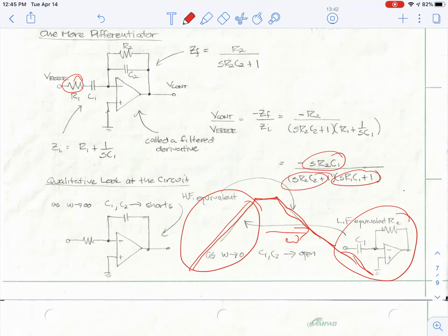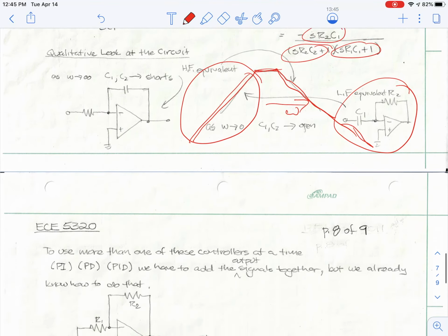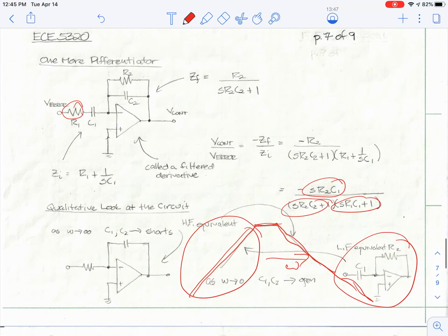And so this is just so you'll know, differentiation in general is a really, really bad idea unless you do something like this. If I take a signal and try to take its derivative, I will amplify any high frequency noise that occurs in it. So if I end up looking at a system and saying, well, in order to get the information I want, I need to take its derivative, be really careful with that.